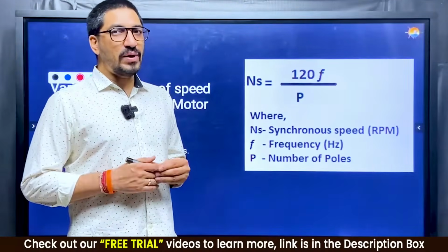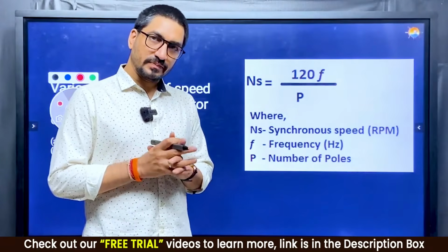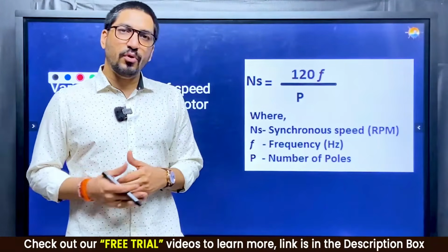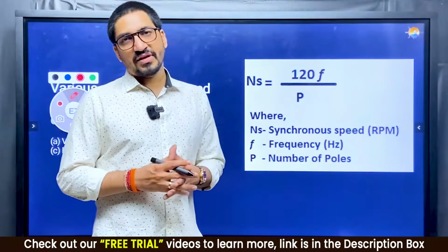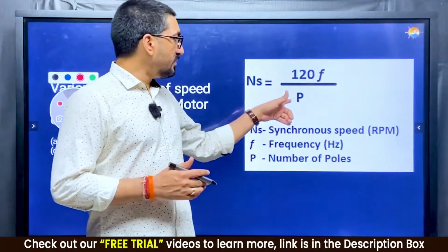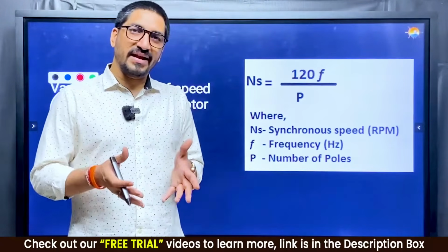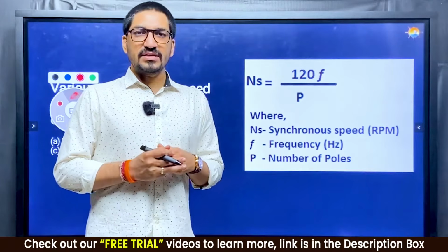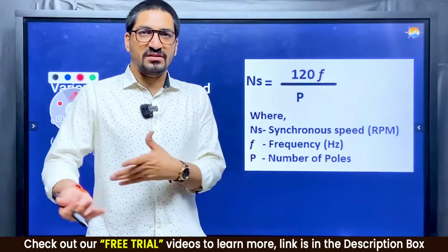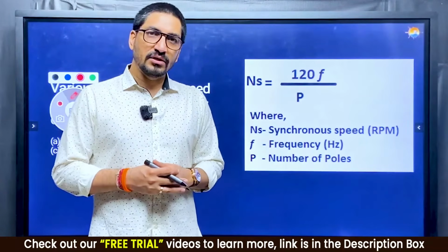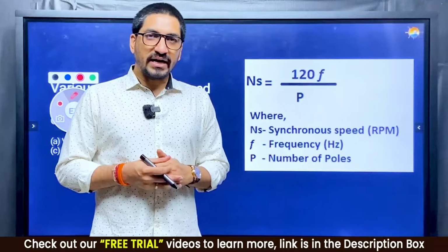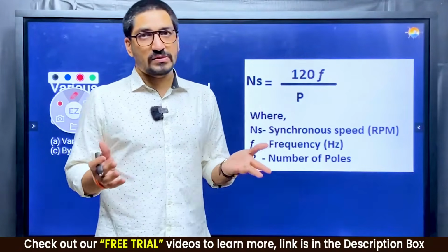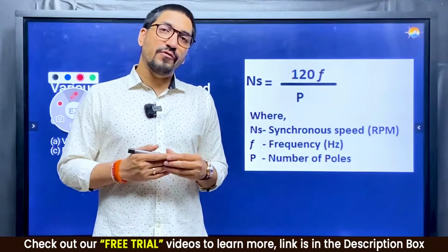On ship, the frequency is 60 Hz, that is fixed. So with the supply frequency directly coming to the motor, we can't change the frequency like that. Similarly, once the motor is made, it is already constructed, then we simply can't rearrange the number of poles in the stator. So that is also fixed. Means synchronous speed is fixed. RMF speed is fixed for a motor.